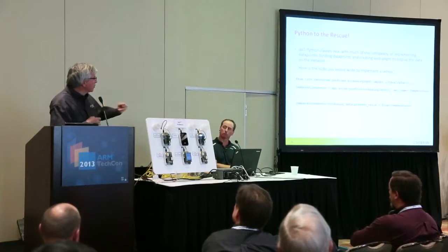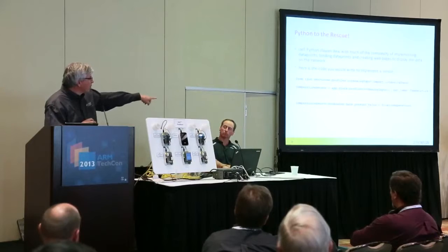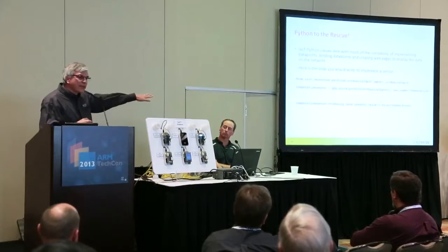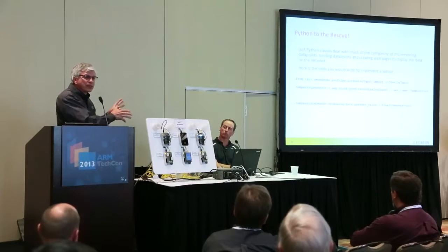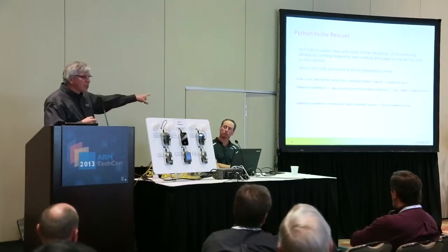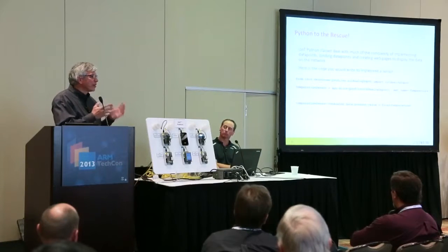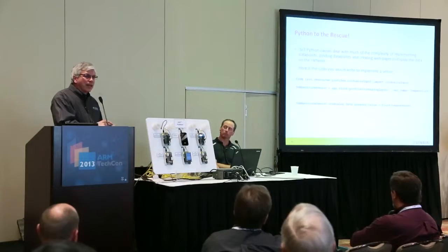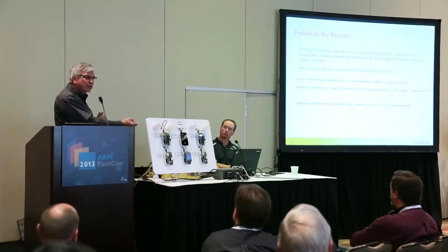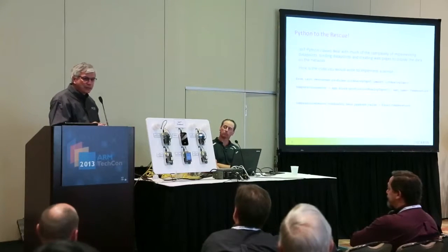Once it reads its value, though, I need one line of code to publish that value on the network. So that one line, the right side is the temperature that I've read from the physical sensor. On the left side is the data point I want to publish to other devices. So any other devices that I'm connected to through those methods I talked about will receive this value. So when I say present value equals float temperature, present value gets updated with that information, and that's all the code that's required from the programmer. And of course, under the covers, a lot happens within the script and within the protocol. But you don't have to write lots of complex code to make that happen.